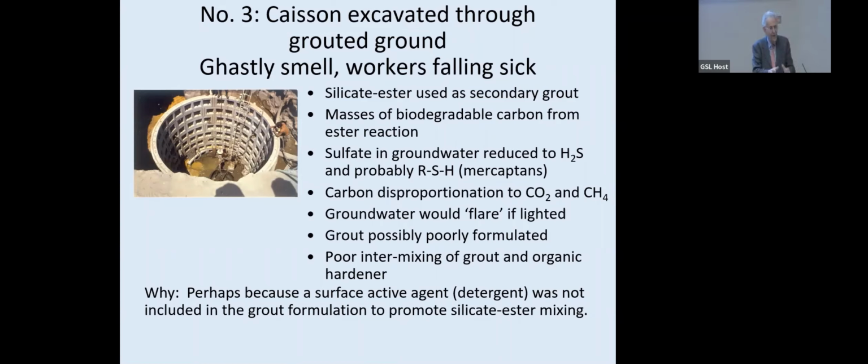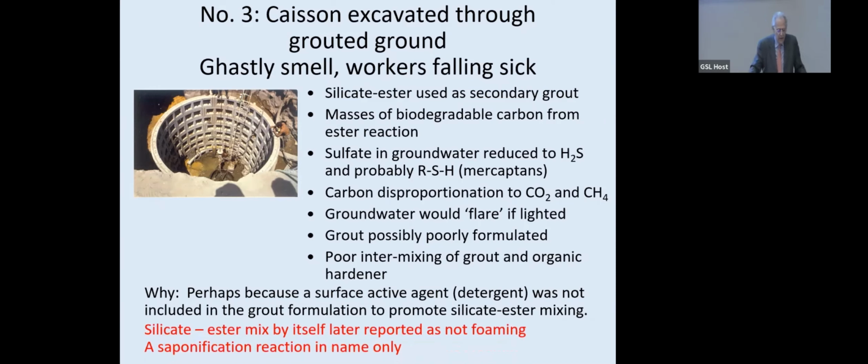It was a deliberate foaming material put in the grout to stop what happened in this case history. But this case history was about 10 years later. So you could say that the silicate ester reaction was a saponification in name only. And in fact, somebody actually went and had a look and it doesn't foam, that particular reaction, without the addition of the foaming agent.